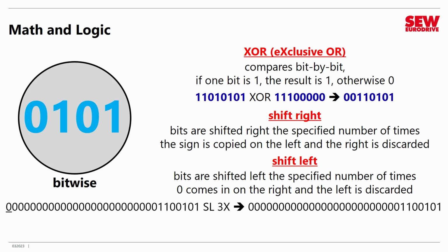So watch the bits closely. Notice that we have zeros coming in at the least significant bit end, and everything just gets shoved down, and the most significant bit drops off the table, and that's the end of it. So if we had some 1s at that end, those could get shoved into the sign bit and cause it to change from positive to negative. But do remember, in most control situations, we're really not thinking about the sign. We're just interested in bits as bits.